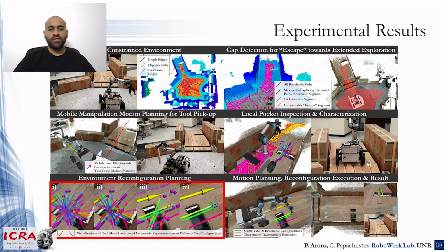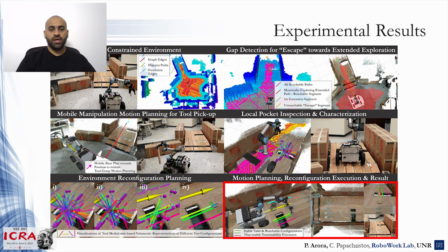Subsequently, only the geometrically valid non-colliding ones remain, and then the physically consistent stable ones, and finally, the surviving ones that actually restore traversability to the unreachable areas after the final test graph evaluation. Lastly, the robot plans and executes a kinematically valid and collision-free arm trajectory that achieves the desired tool placement, successfully restoring the terrain traversability to the other side of the gap.